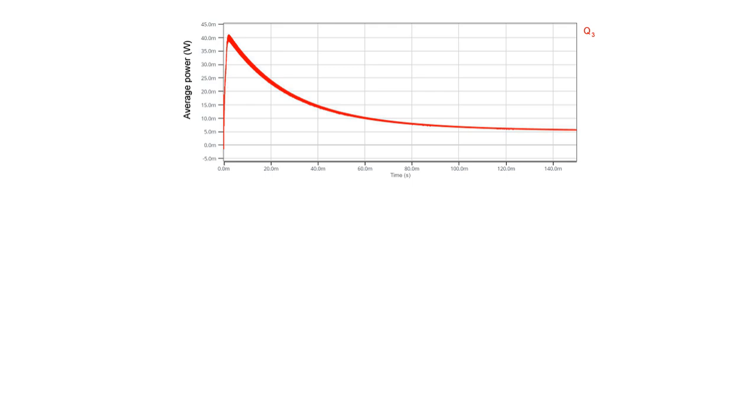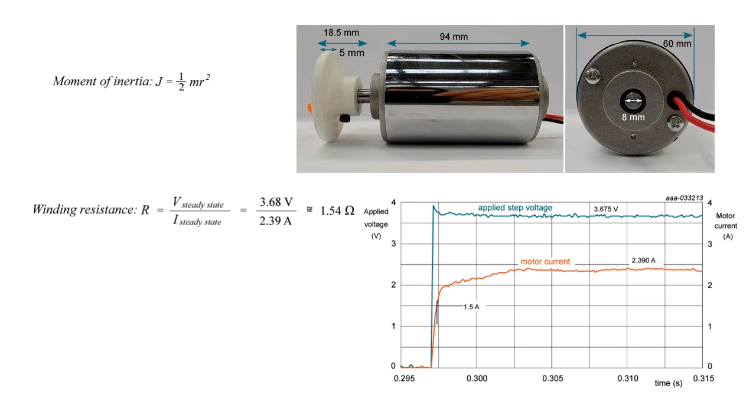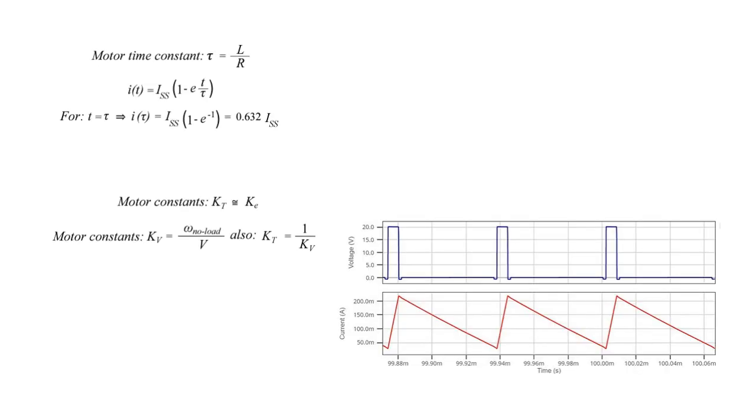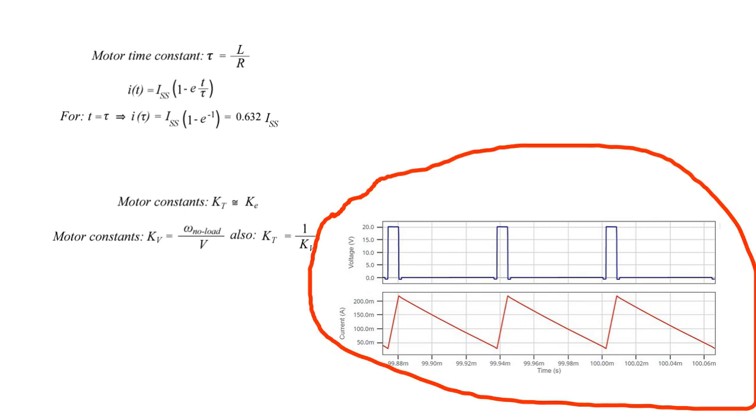Because in your home, RMS measurement is the way, but in the motor we have this type of current value. In reality, our voltage value is like this one. You can see pulse on, pulse off, pulse on, pulse off. If you use a multimeter, you can measure the RMS value of this signal. It is a very bad solution. Okay, this is just a technician approach. You must use an oscilloscope. Okay, actually your current value is like this one, a triangle.